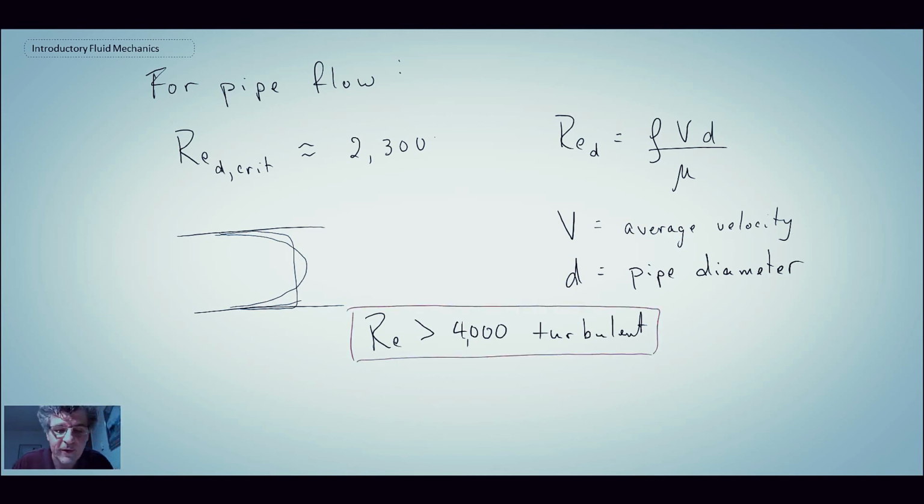However, I have also heard that experiments can be conducted where you can get Reynolds numbers as high as 10,000 and you still have laminar flow, but I think that would be a very, very specially designed experimental apparatus where you minimize all instabilities, all disturbances, and it would be very, very difficult to replicate anything like that industrially. And so that's more just a scientific type investigation.